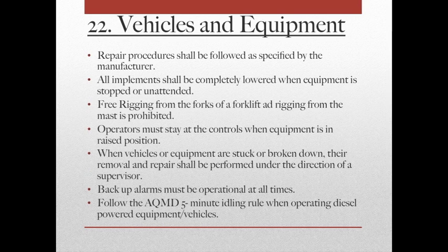Repair procedures shall be followed as specified by the manufacturer. All implements shall be completely lowered when equipment is stopped or unattended. Free rigging from the fork of a forklift and rigging from the mast is prohibited. Only approved attachments such as a jib or lift hook shall be used. Operators must stay at the controls when equipment is in the raised position. When vehicles or equipment are struck or broken down, their removal and repair shall be performed under the direction of the supervisor. Backup alarms must be operational at all times.